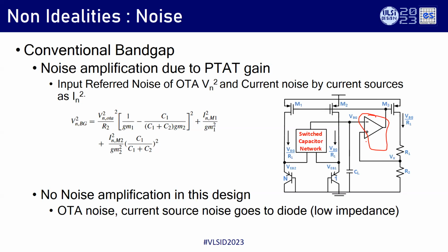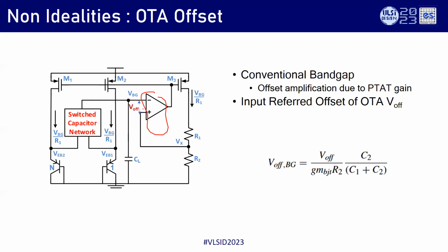Yeah, that's a good question. But that's not only the scenario in this band gap, that's common for everything. My point so far has been how the offset of the op amp will be amplified, and that has been solved. Now coming to your question, let's say this is our band gap. Mostly we put a decap, which solves many problems. Provided you have enough decap, these two are synchronous. So now if the switch cap has any noise on this ground, that will go here, right?